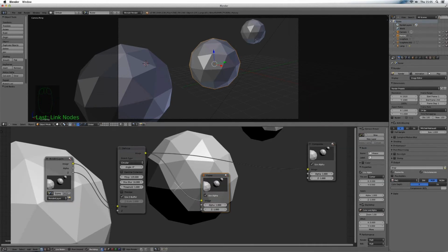I usually use that so that I can scale it properly on the top, but we'll just use this for now. So what we need to do is change the depth of field, because at the moment it's kind of shallow. It's not shallow, it's really wide. There's no blurriness. So for a start, all we're going to do is change the f-stop, which is this top line here. And these usually correspond to f-stops on a camera, if you know what those are.